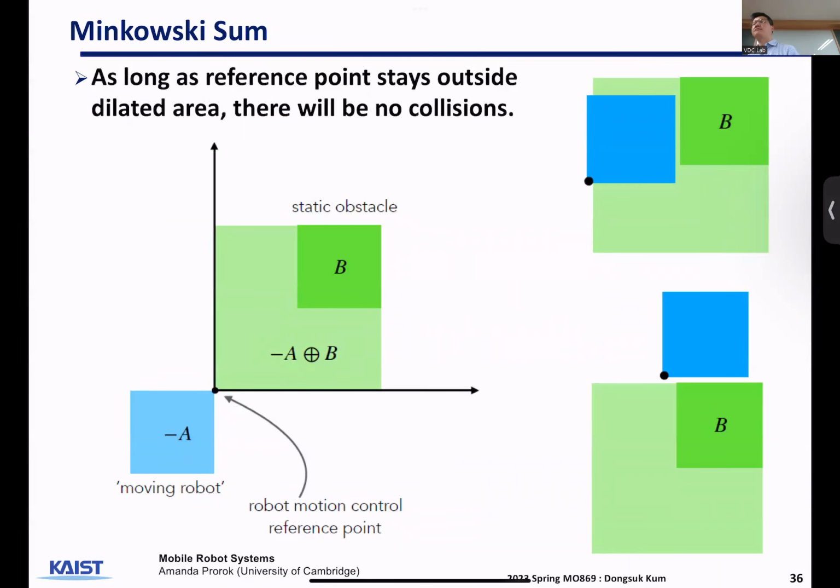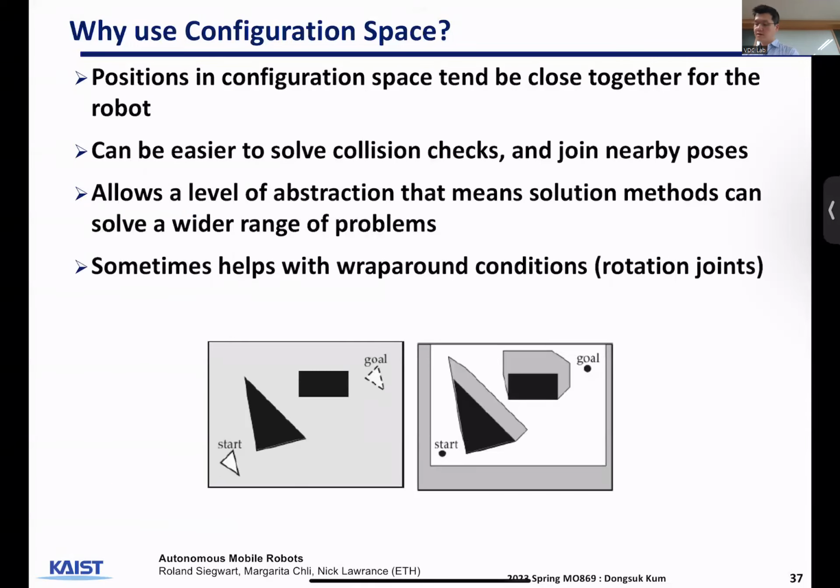But if it's not symmetrical, then things can become a little more tricky. Anyway, this is one technique when it comes to computing the obstacle space and making your robot a point. That way you don't have to worry about your robot space versus the obstacle space. You lump that into one side, and then just make your robot position a point.